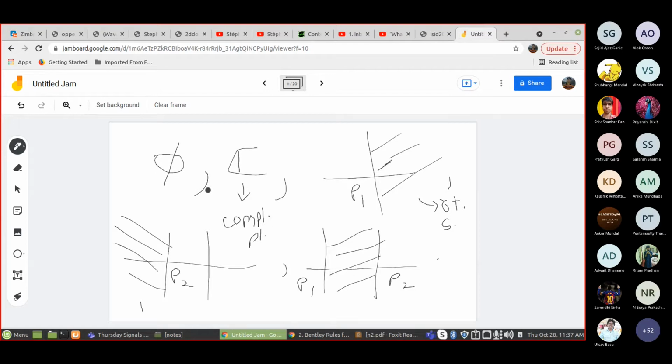Okay, for both sided signals you can have this finite strip, finite along the x-axis but infinite along the y-axis, or it can be empty. Okay, so for causal signals ROC will never be empty, and can never be this also. Causal signals can have this as ROC or this as ROC. Anti-causal signals can have this as ROC or this as ROC. By anti-causal, I mean they are identically 0 for positive T, only exist for negative T.